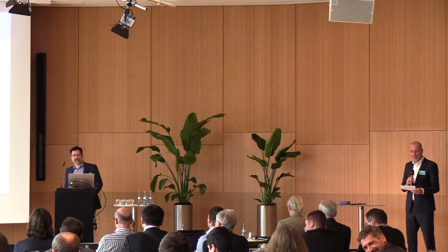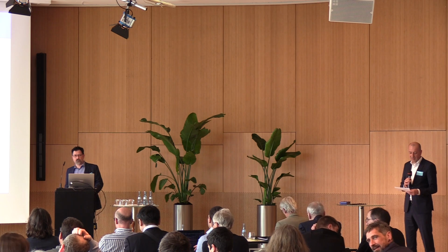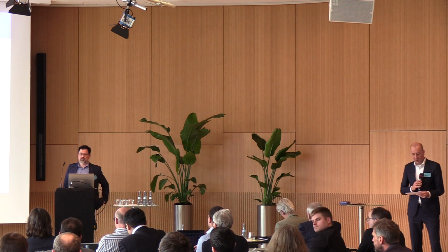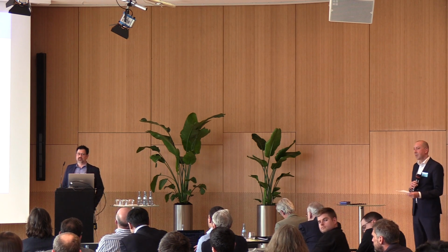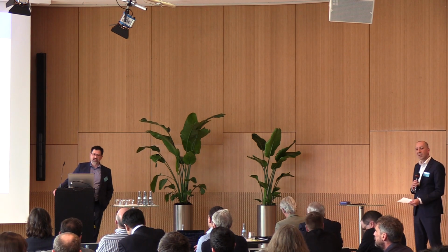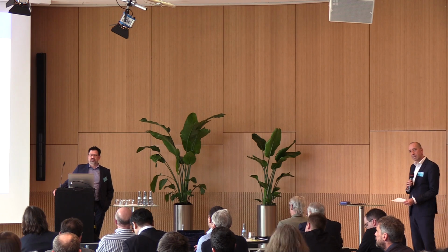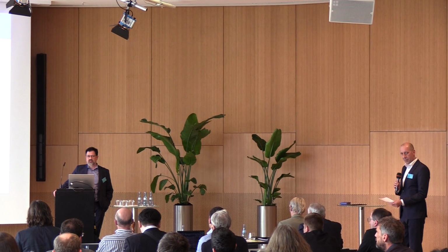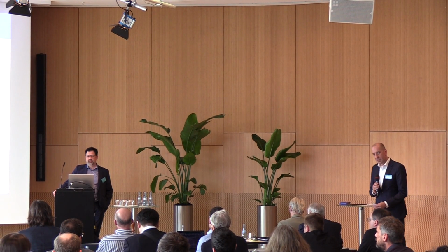You said when you're in one situation you can change the material. I guess that is only the fatigue properties that you then change. So if you want to change really a material class, let's say you want to test gray cast iron or nodular cast iron or CGI, then you really have to change situations, system behind, and so on, correct?